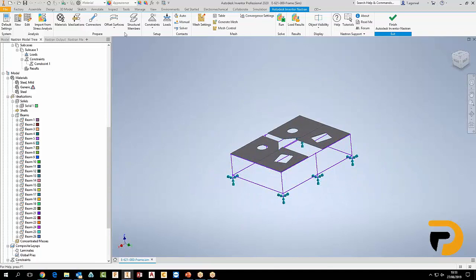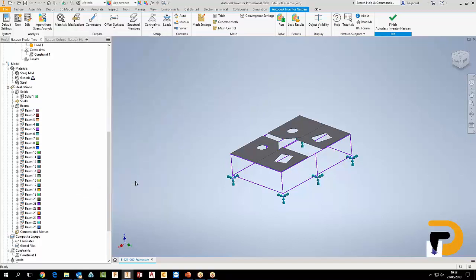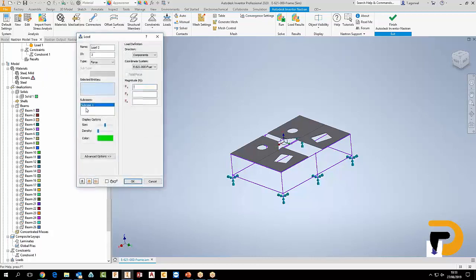I'm going to use loads. I'm going to create two loads. One is gravity, -9810. And just for those people that are on the webinar, the minus values also indicate the direction along the Z. Exactly. So the minus is going to go obviously in the negative. So you can see by the arrow indicating towards the bottom of the right-hand screen where G is the arrow pointing.